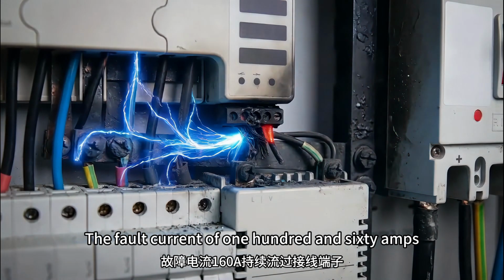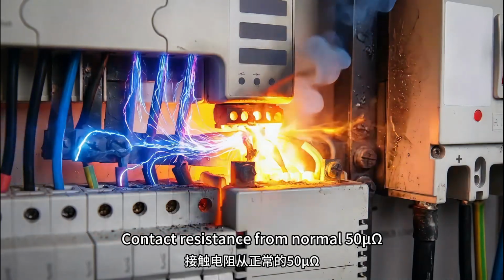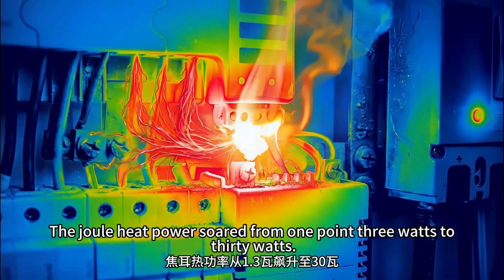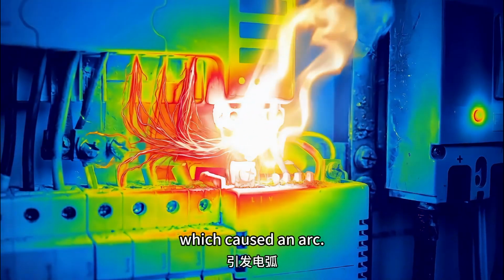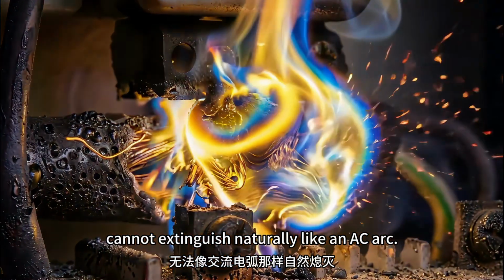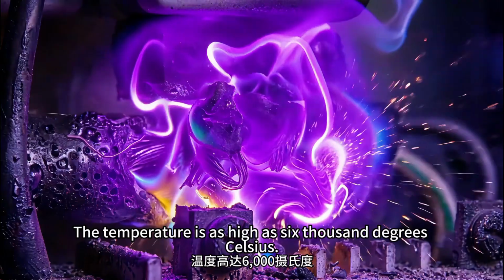The fault current was 160 amps. Contact resistance gradually increased from a normal 50 milliohms to 12 ohms. The Joule heat power soared from 1.3 watts to 30 watts. The temperature rapidly exceeded 200 degrees Celsius, which caused an arc. The DC arc has no zero crossing point and cannot extinguish naturally like an AC arc. The temperature is as high as 6,000 degrees Celsius.